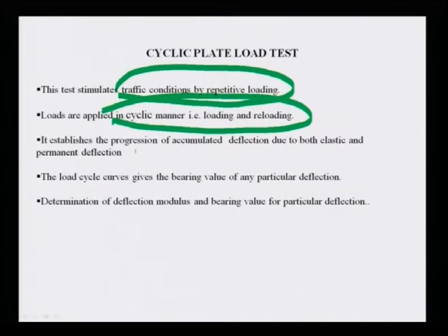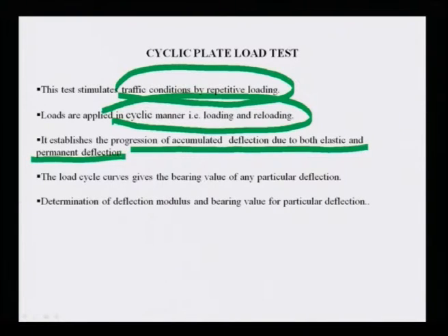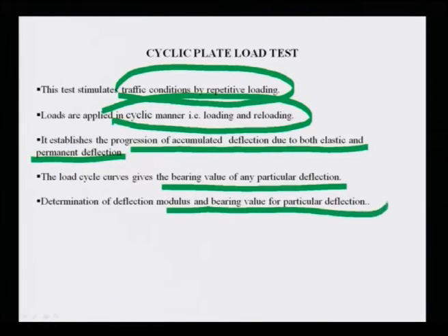It establishes the progression of accumulated deflection due to both elastic and permanent deflection. The load cycle curves give the bearing value at any particular deflection, and you can find out the deflection modulus and bearing value for a particular deflection. Why is this cyclic plate load test required, if somebody asks? It is basically to simulate the traffic conditions by repeated loading.